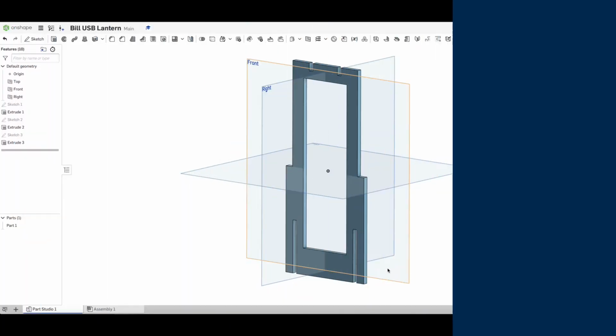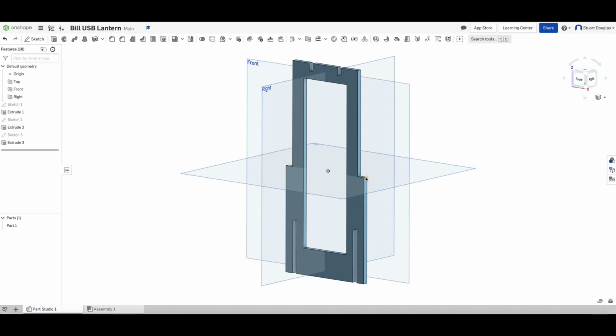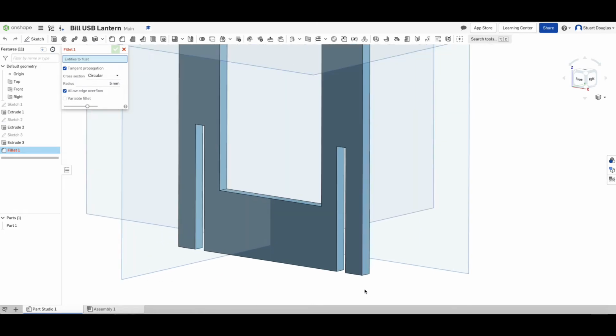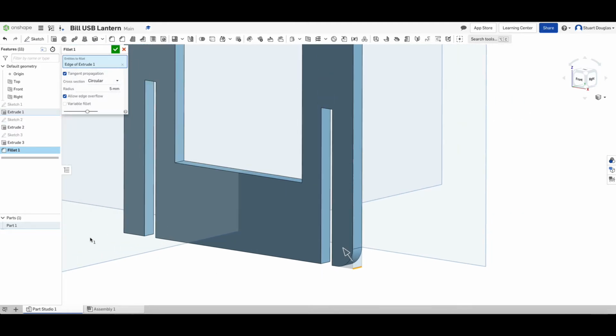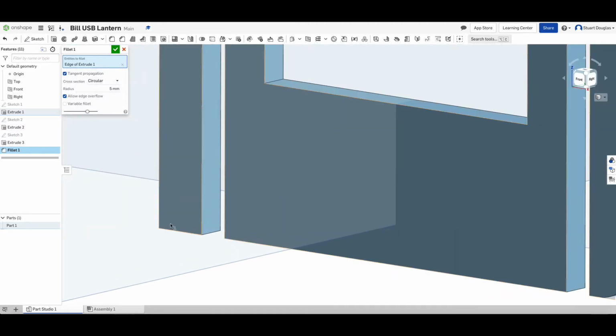We just want to soften our panel by adding a couple of rounded edges to this corner and the bottom edges here and here. To do that, we go to our feature menu here and we can edit by applying a fillet, or Shift and F. Going to zoom in to help me select the right edge, and I want to pick this edge here. I want to zoom out, zoom in, because I want this edge.